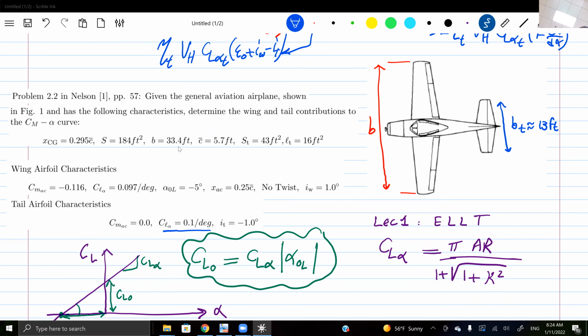So you are given the actual B is 33 feet, and you will use your ruler to measure B from the drawing. You can divide these two numbers to get that scale. Once you have that scale of the drawing, I can get any distance that I like from the drawing. Oh, I get it now. Thank you, Professor. You're welcome.